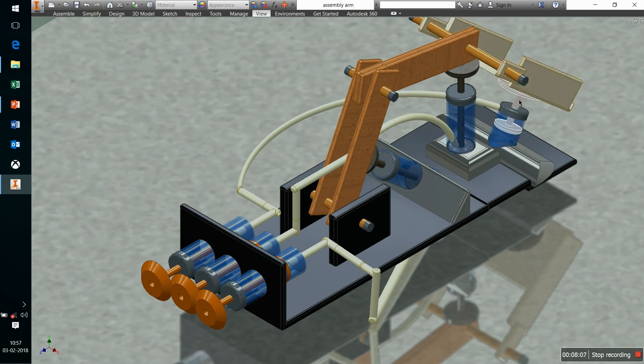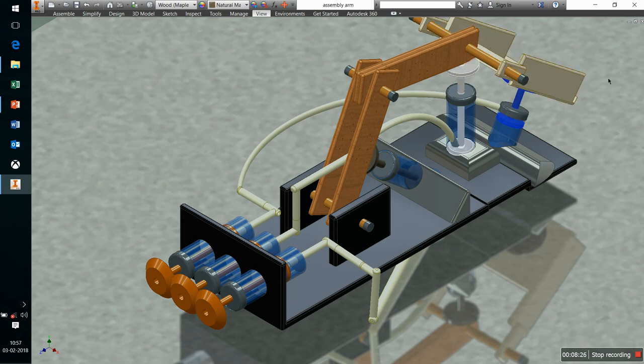So this piston must be moved. That piston cylinder arrangement is connected to cylinder arrangement 3. When I'm applying some amount of force on piston 3 like this, I will be getting some force at this end, so I will be lifting this arm. This is how it works.